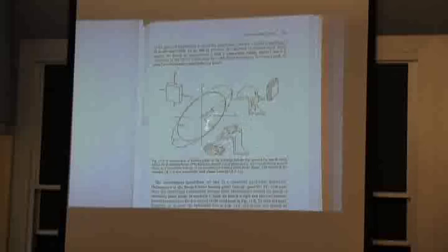The other place where I have plane strain is where I'm squeezing in one direction and pulling in the other direction. So this is the same drawing tension, this drawing tension here as I'm drawing the cup. And that same tension is sucking in the flange. And I will get plane strain here, but that's down in this loading condition.